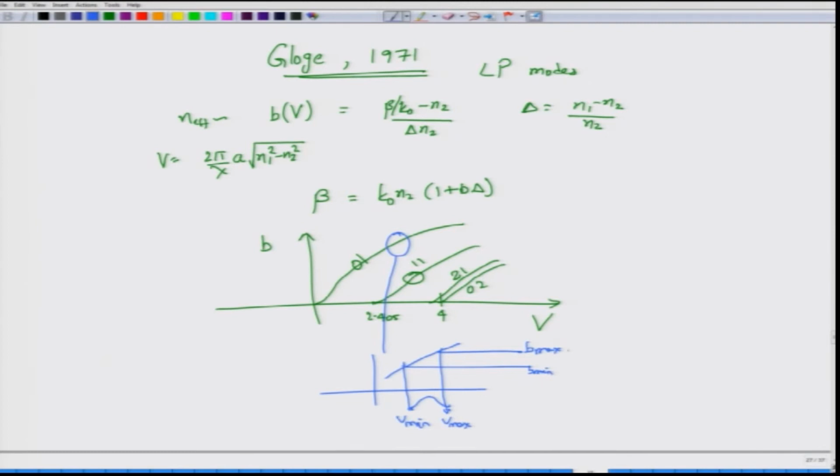The relationship here, say B0 with V0 as the center, is not an exact replica of this one. So, it is not a linear relationship, and because of it being non-linear, the propagation constants actually depend on what lambda you are transmitting or on what pulse width you are transmitting, and most importantly these parameters are now further functions of V, and the derivatives of these are what is going to give you the dispersion in the fiber.